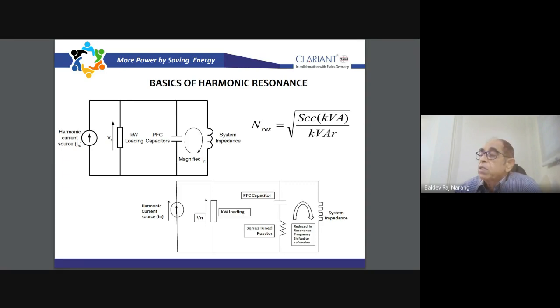So what is happening is this harmonic current is flowing through the capacitors and also going to the transformer and back to the utilities. Capacitor being a reactive load, the impedance is inversely proportional to the MFD value: like we have inductor 2 pi FL, here it is 1 upon 2 pi FC. As the harmonic frequencies are very high, the capacitor draws the harmonic current. It offers a very low impedance, so it is drawing the current. So this is the first item which fails.